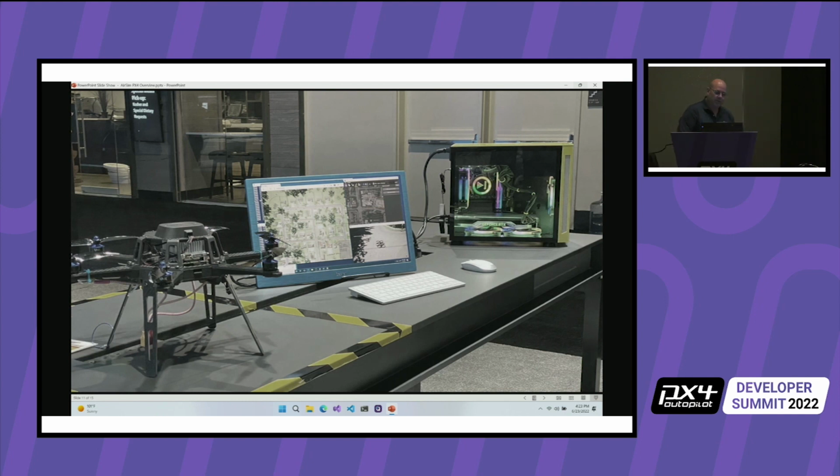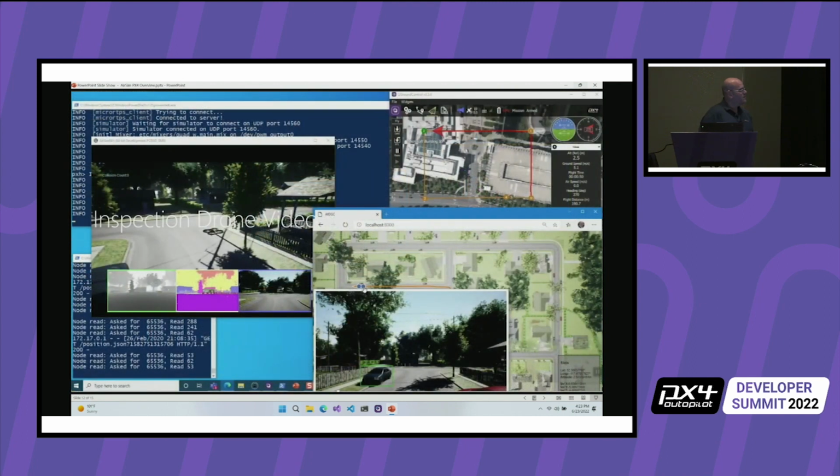Okay, so this one, there was a lot to this demo, right? Because basically everything you saw on that architecture slide, we implemented here. And we implemented everything in this case as Docker containers. And so you'll see as I run the demo that we'll start spinning up the Docker containers. But what happens is we're reading the sensors in ROS that are being published by AirSim and by PX4. And then we fly the neighborhood using QGroundControl to map out a path around the neighborhood.